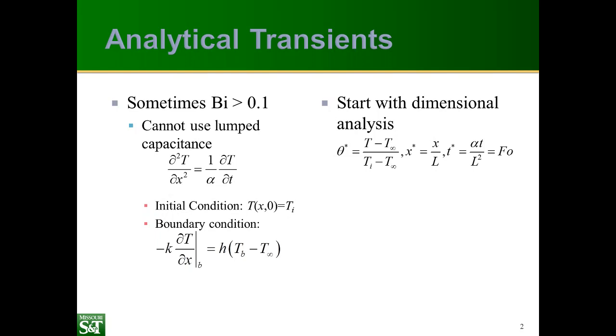So we look at this simplified version of the heat equation. What we've done here is eliminated heat generation. We're ignoring heat generation, and then we've divided through by rho c to give us this equation. Now, we have a time-dependent term here, so we need an initial condition, and we also have an x-coordinate, so we need two boundary conditions.